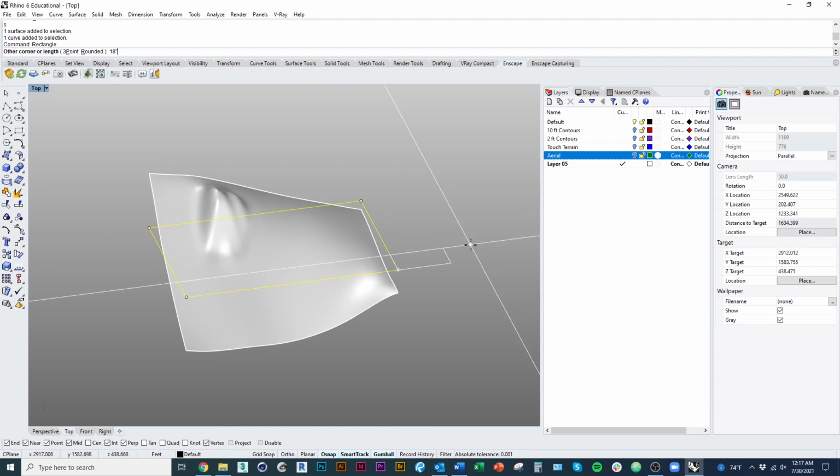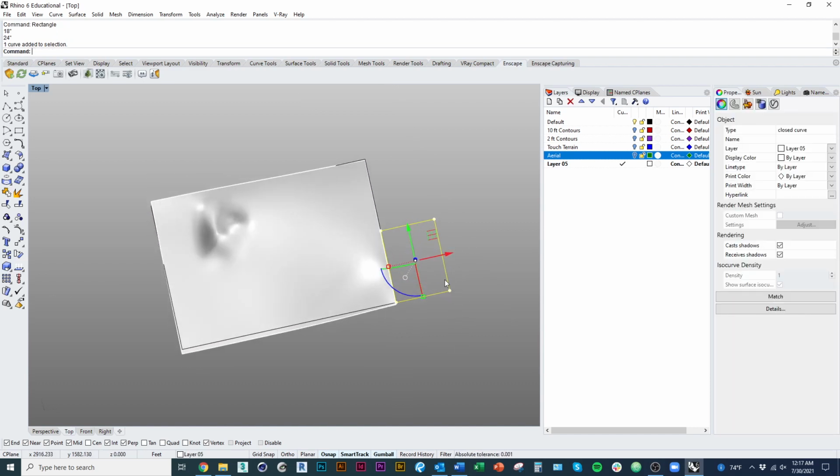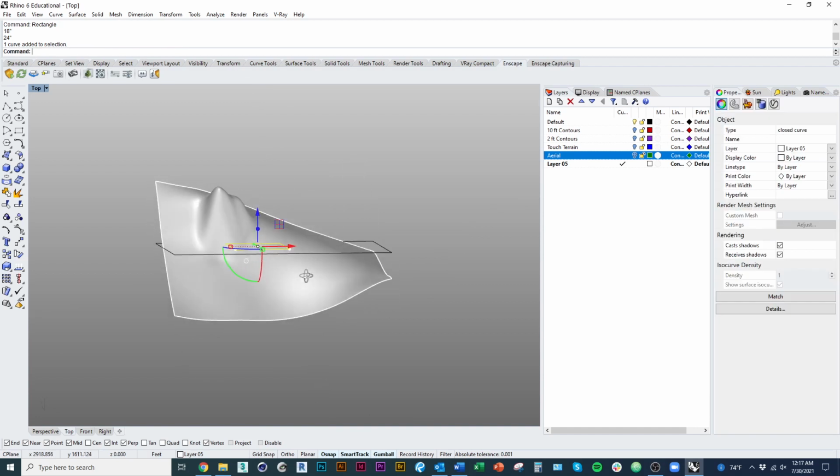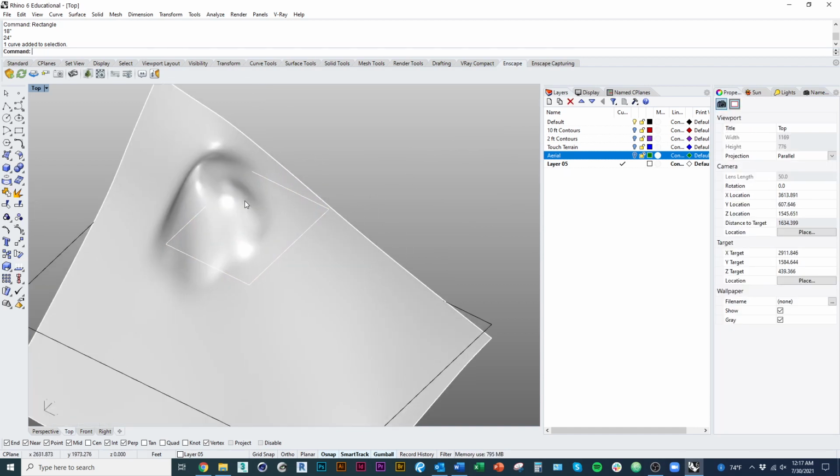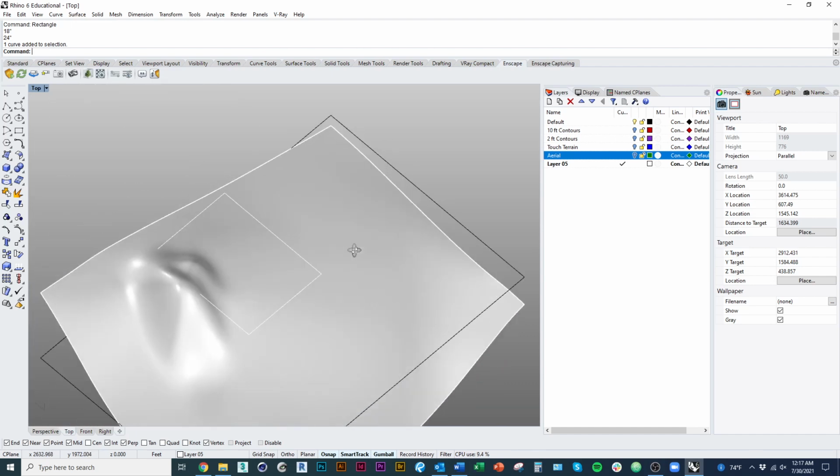That tells Rhino I'm entering units of inches rather than feet. Then I'll do, I don't know, 24 inches, and I'll write quotes. Okay, so that's a new outline with the dimensions that I want. Whatever that size is, you'll choose it to make sense for your particular project.